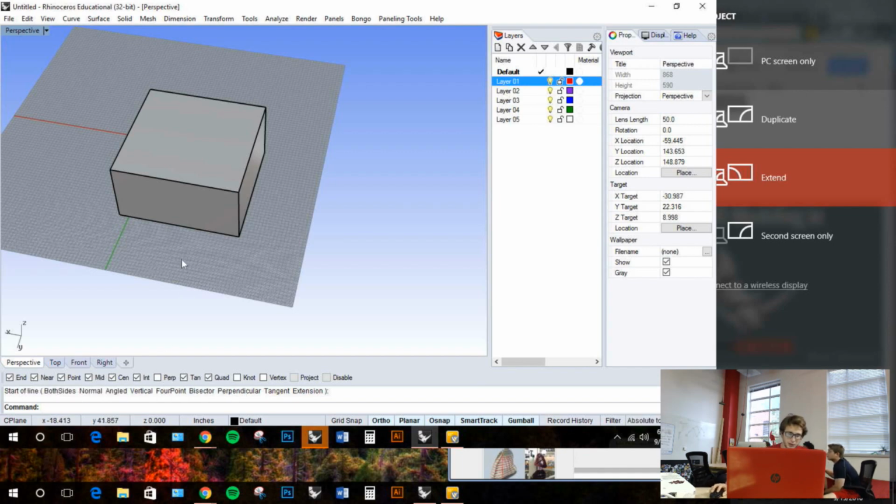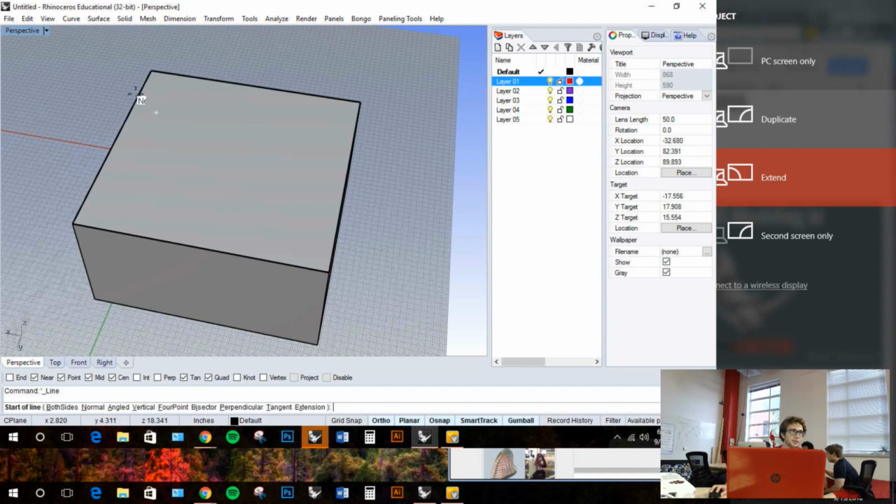And essentially, so say I take off end. So this is an intersection of two lines. If I take an int, all I get is near this edge. I'm not getting an object snap for this corner, really. So you can toggle which ones you want, and they can be very helpful at times and annoying at others. If you have a lot going on in your model, there might be too many things that your cursor is snapping to, so you can disable some. All right, does anybody not have the object snaps at this point?